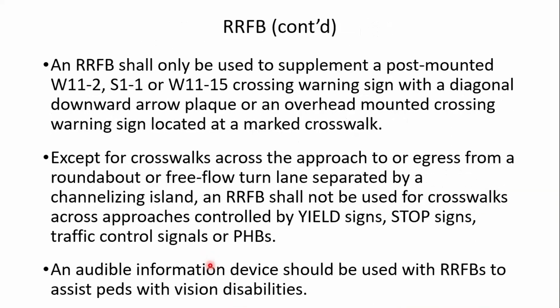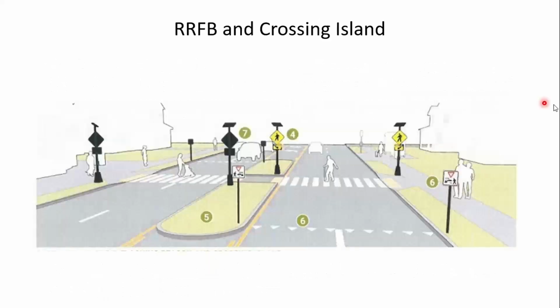Thanks, Ron. We do have a question number 9 from Kyle. Kyle says, I believe the MUTCD states the RRFB PHB can be used on uncontrolled approaches to unsignalized intersections. What is the recommendation of pavement markings for far side approaches that would stop within the intersection?